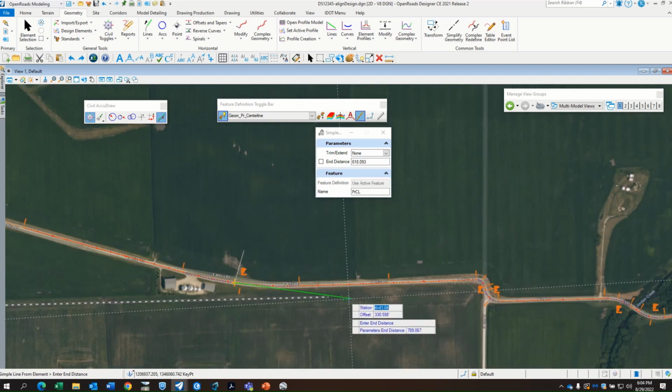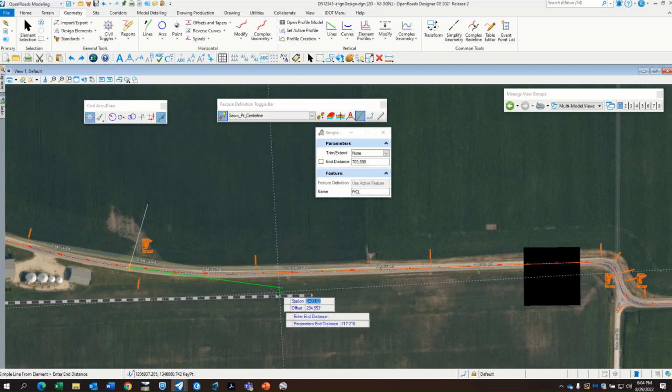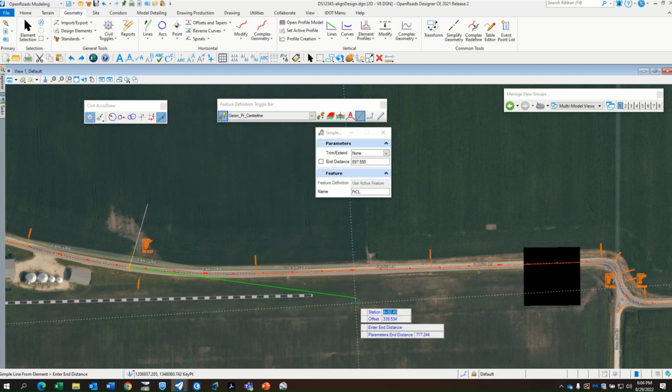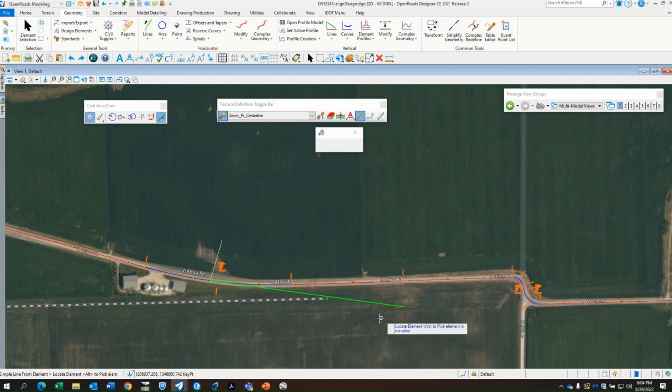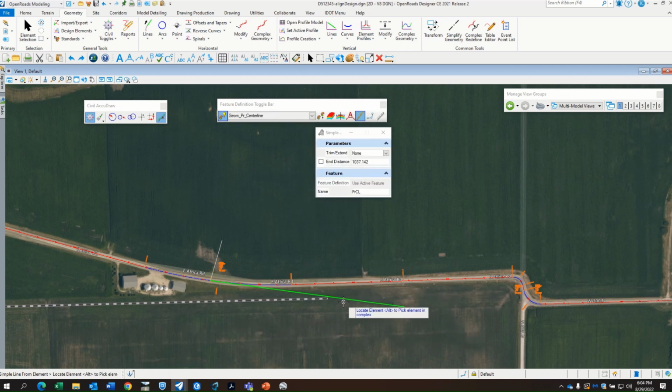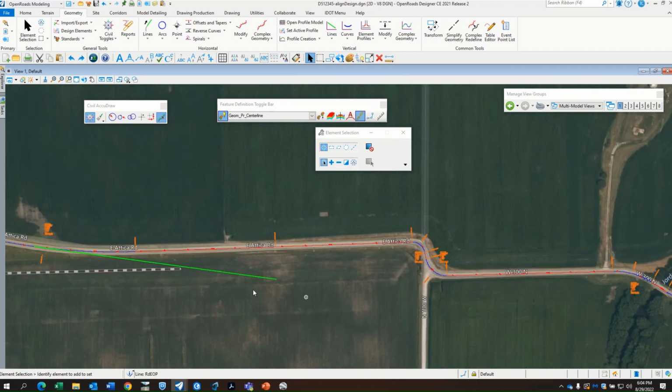And then you can see that I'm pulling a line tangent from that exact station. And so, like I said, the length is going to be adjusted later. So I'm just going to randomly go out here somewhere. And data point to accept. And trim, none. And that's it. We're not going to need this other line here anymore. I'll go ahead and just delete that line.